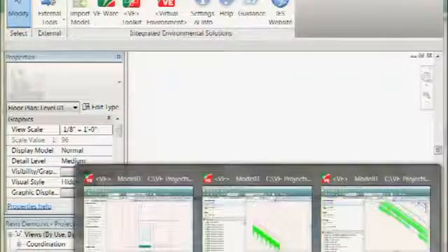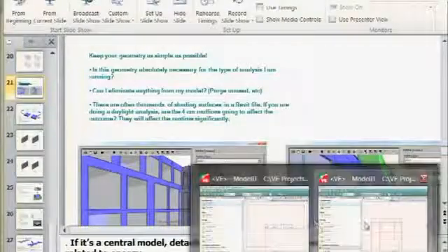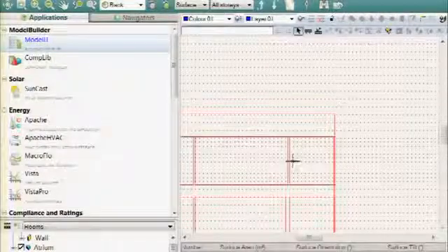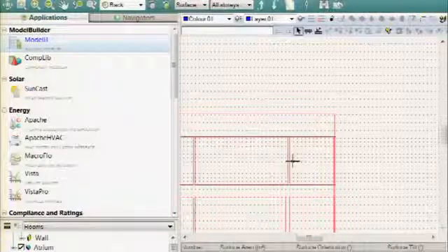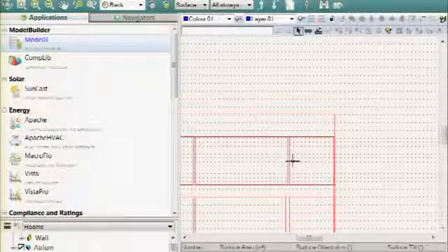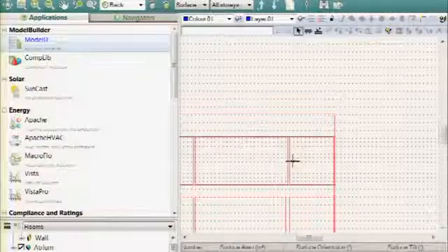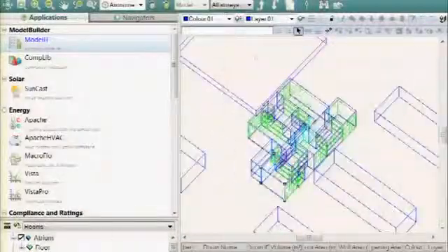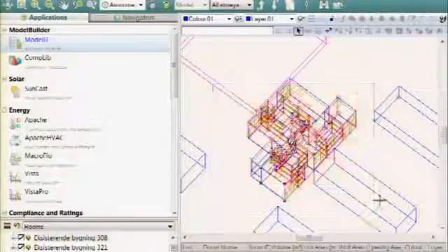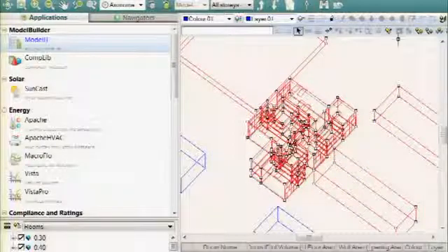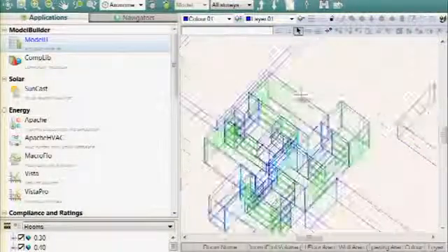If I'm inside of the VE and I actually turn off my inner volumes and then rebuild them, they will look almost completely different, because then it is based on the construction. So if you have set up your inner volumes in a way from Revit specifically, make sure not to turn them on or off, because it will rebuild them with a different view. So if I was to highlight this model, for example, that I worked on, and turn off my inner volumes and then turn them back on, they would rebuild based on constructions. But the way they're built now is based on how the Revit model is built, by those center lines.